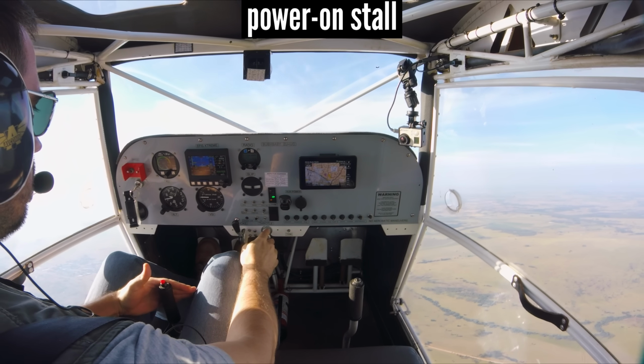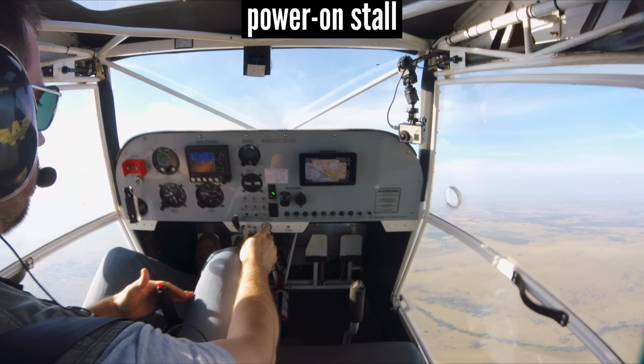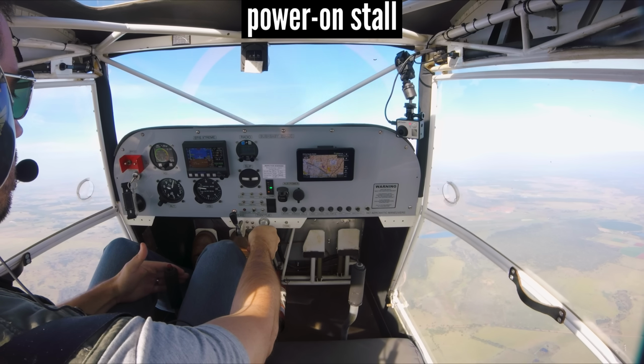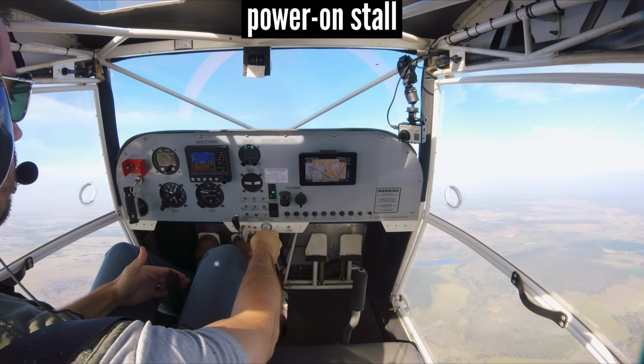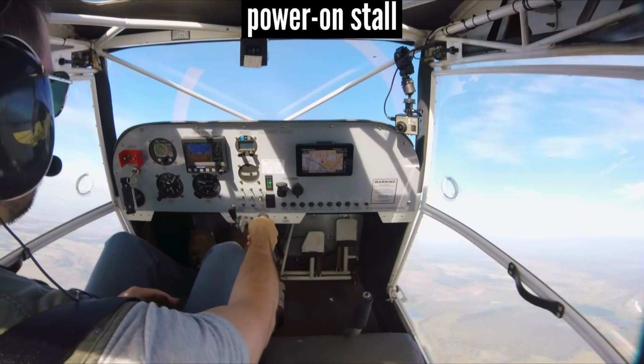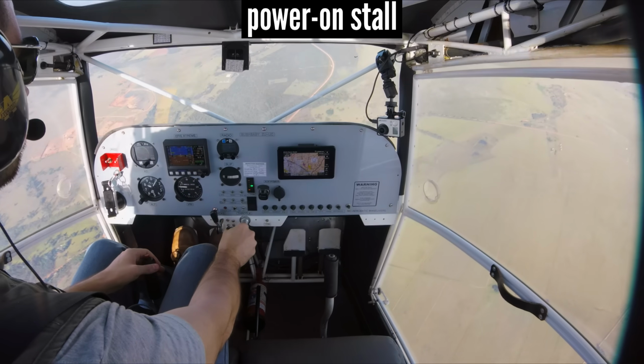The plane may descend rapidly, but the wing won't stall. This principle applies to all airspeeds, bank angles and attitudes. A stall only occurs when the wing exceeds critical angle of attack, and that can only happen with the stick pulled nearly fully back. Keep in mind, doing a power-on stall can make the plane stall with slightly less up elevator, as the prop wash blowing over the tail gives the elevator additional pitch authority. But the fundamentals remain the same. That stick needs to come most of the way backwards to stall the wing.